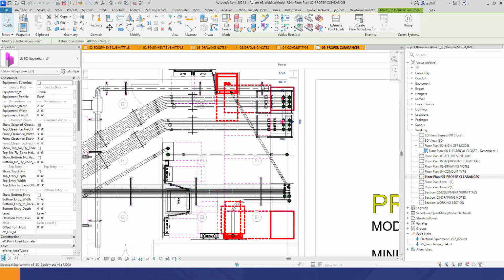of things. And with the original layout here, with our switchgear, in the original coordination, these were only 3 feet long. In actuality, it's a 5 foot working clearance for this equipment. And as you can see in these two instances, our gear no longer fits in this room.